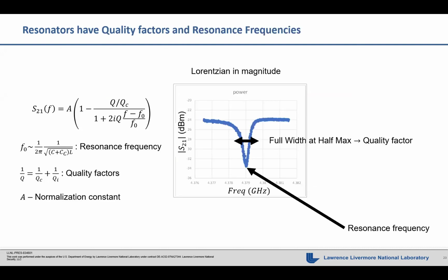We can also probe it. This is transmission, so over here we're looking at transmission as a function of frequency. This oscillator looks like a filter, either a band pass or, in this case, a band stop filter. You load it up with energy right when you're hitting it with the resonant frequency. There are two main important parts for the circuit. One is the full width half max, how much loss, how accurately you can get the frequency for the circuit, and then the resonant frequency for it.